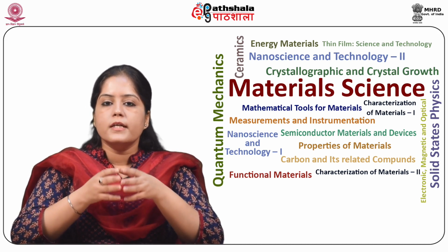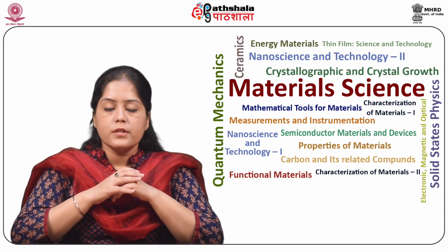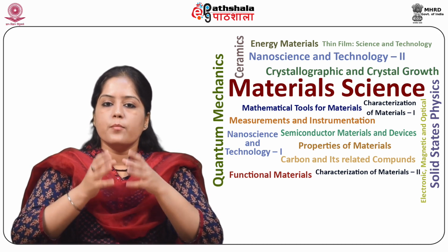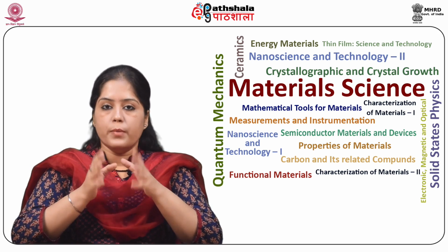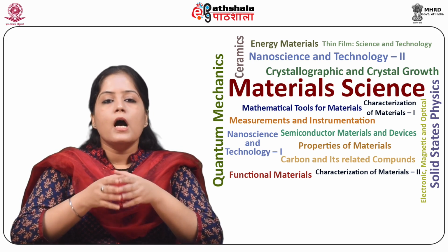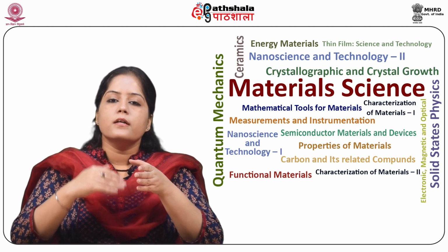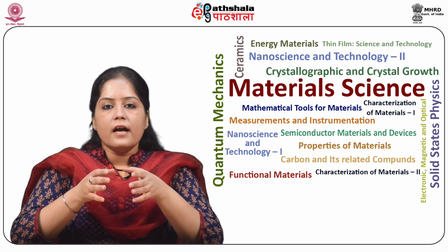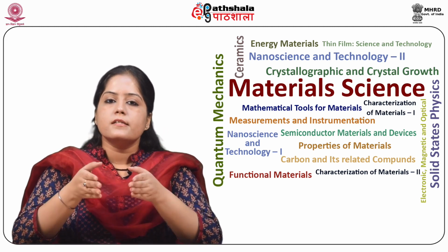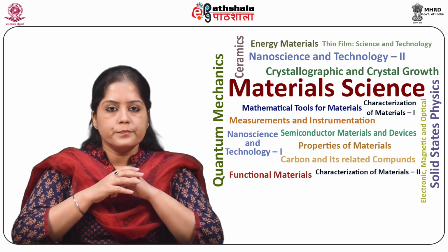Recently, device quality oxide-semiconductor interfaces have been developed on silicon carbide, a wide band gap semiconductor with excellent bulk properties. Here the problem with the interfaces is due to the dangling bonds, the atomic bonds at the semiconductor surface, that have to be electronically passivated to enable the existence of mobile charge at the semiconductor surface.